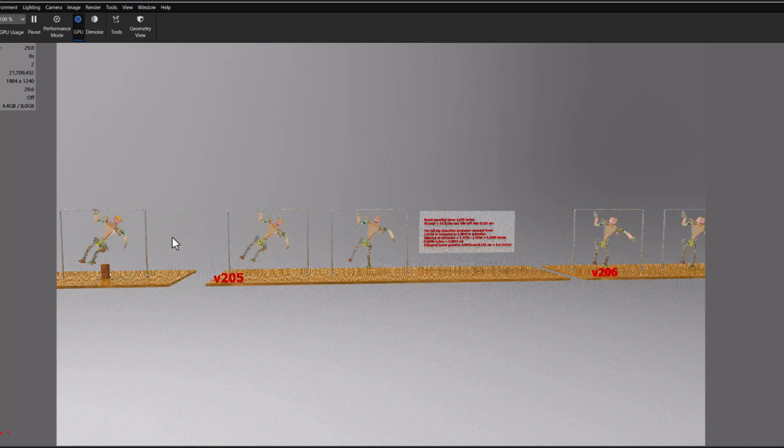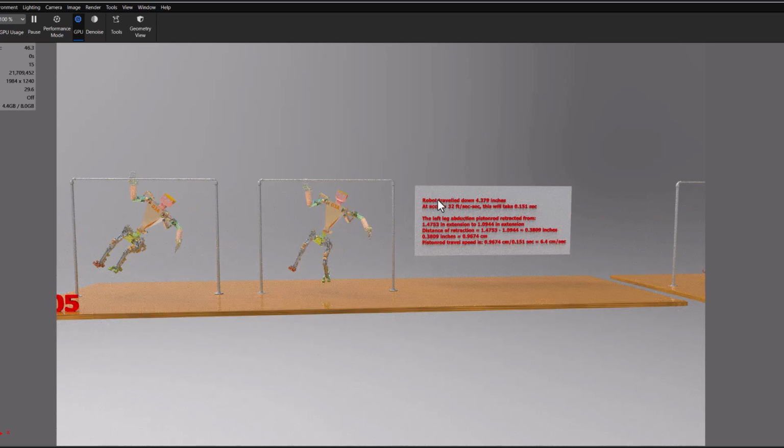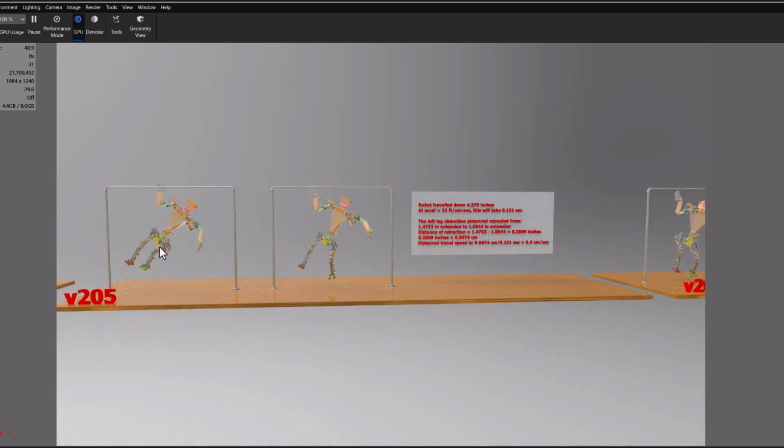That's the next part. And this is a little discussion of, at 15 centimeters per second, what happens is this left leg gets abducted out away from the midline, and the right leg gets adducted in towards the midline, and the robot tilts its thorax a little bit to get itself in a position to land, which the robot can do if it's a hydraulic cylinder robot, and the electric motor gearhead robots can't do that. They can't do that with a 187-pound robot.